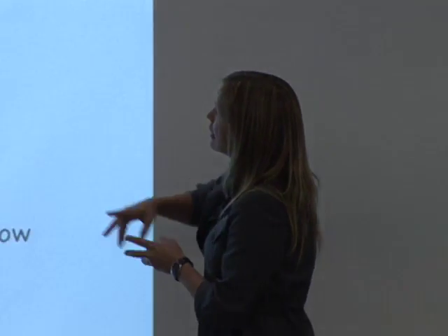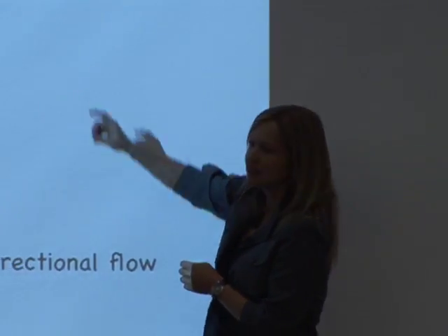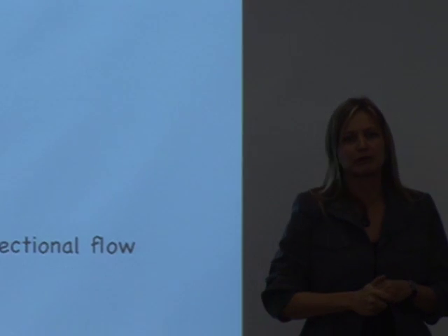Here are some of the specific issues that you'll have with a water turbine. Blade strength, fatigue, and vibration issues are one, a much, much bigger problem than in wind turbines. Another is that when you go in the coastal area, for example, you have changes in fluid density that are non-negligible.